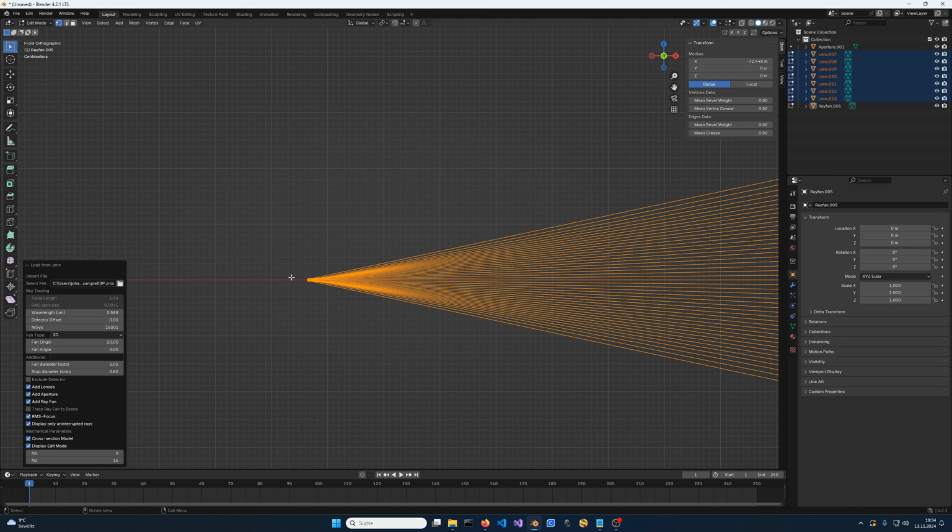Now, here's a bit of a discrepancy between the zmx file and the patent itself. I've looked up the patent of this lens online, and between the nominal image plane indicated in the zmx file and the description in the patent, there is a 50 micrometer offset. And if I apply this 50 micrometer offset, then this places the image plane pretty much exactly where we'd get the RMS focus for this 2D beam.